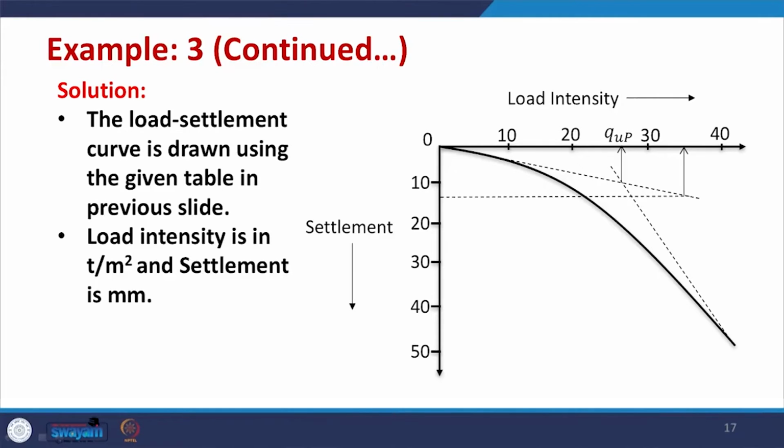You can see that this curve is not linear. Initially when you increase the load, the settlement increases a little bit; however, after that the settlement increases exponentially. As a result, you can divide this graph into two components.